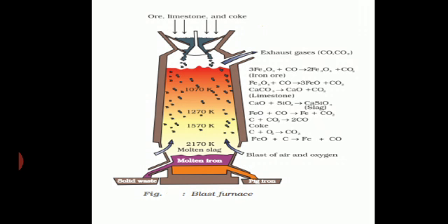Here the pig iron is poured into a special type of pear shaped converter, which has an unperforated solid base lined with magnesite, and pure oxygen is blown from the top.